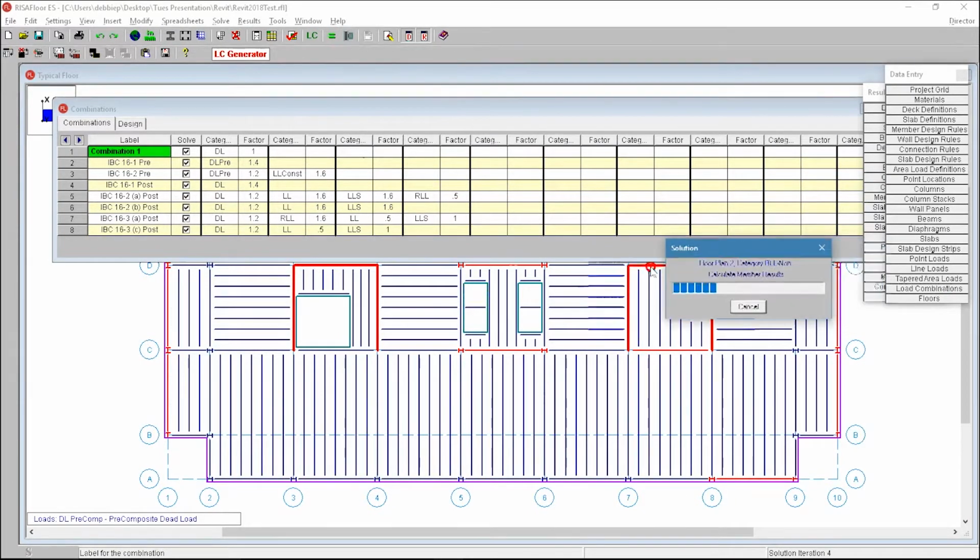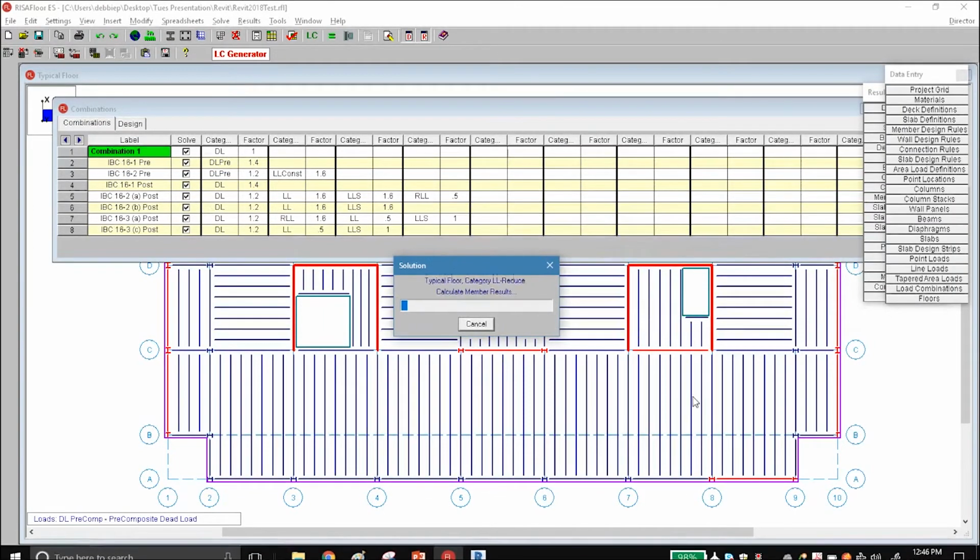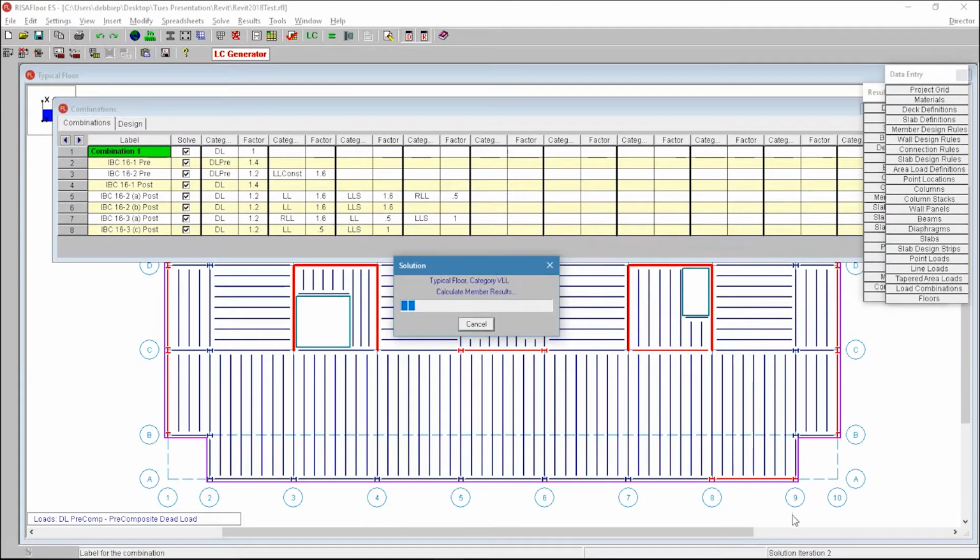The program is going through an optimization routine as it runs, carrying all those gravity loads down the structure, finding the best possible solution, and iterating a little bit as it goes. At the bottom of my screen you see the iteration of the solution, because when we think about design, the members get sized, then loads distribute slightly differently, and we have to size things up and down based on those loads. So we're doing a full iterative design of those members, floor by floor, carried down.